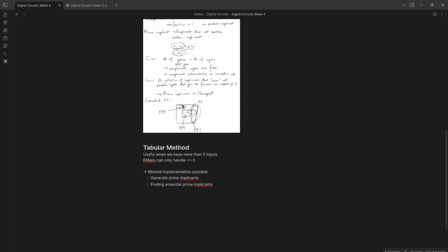We're trying to find the implicants that cover inputs that no other implicant covers. So continuing in that vein, if our cover basically covers all possible valuations or inputs, then we are done. If not, then we continue until we are done.